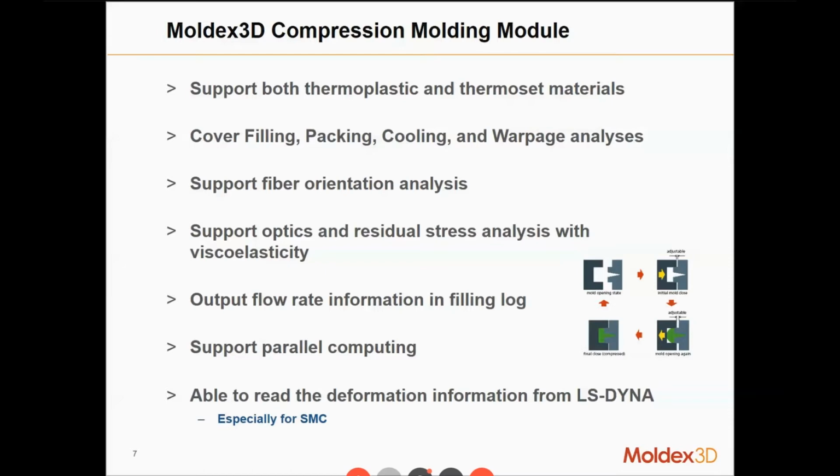But in the beginning stage of SMC compression molding, it's more related to solid dynamics, which is why we recommend this kind of workflow: for SMC we start with LS-DYNA to calculate the large solid deformation in the beginning stage. After the sheet molding compound is largely deformed and has a shape closer to our mold surface, and has also reached a higher temperature, a more fluid stage, then we can export this data from LS-DYNA, import it into Moldex3D, and continue the calculation and finish the whole compression molding process for sheet molding compound.